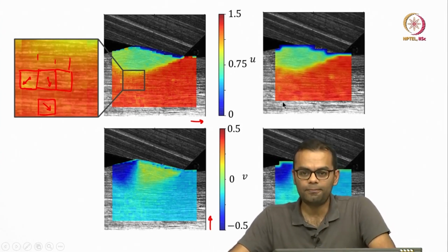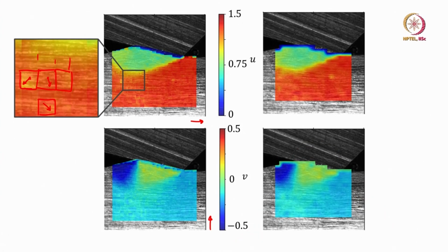And so, in order to get a better version of the actual displacement field, you have to do some post processing, and typically the type of post processing you would do is linear interpolation or higher order interpolation if you want smoother fields. Now, the main problem with this of course is that when you do interpolation you are losing some information. So, remember at each of these points this is accurately determined from an actual cross correlation match, right, for a 6 dimensional vector. But when you do interpolation you are losing that information which is recovered from the search scheme, and so how much interpolation you do is a trade off between how much you are willing to sacrifice at the expense of a smoother field, right.